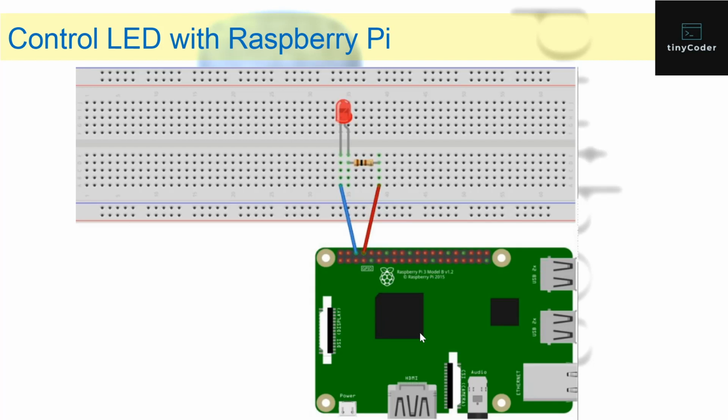You can see here's the Raspberry Pi, and here's the circuit, which I'll explain later. But what is this thing around it? That is what we call the breadboard. You can see that the breadboard has some holes here. These holes over here in the circuit area are all connected vertically, from up to down like this.